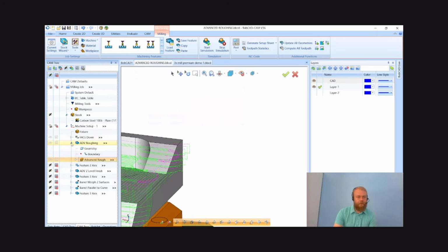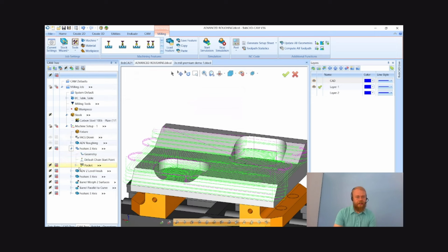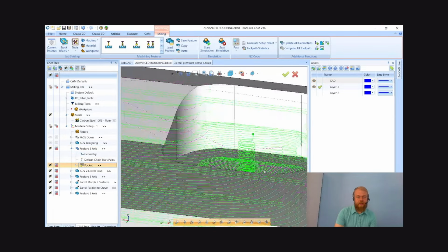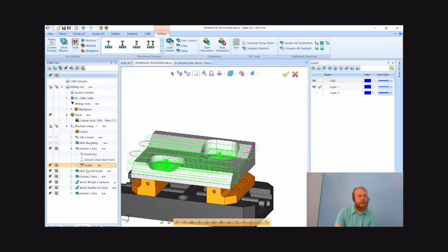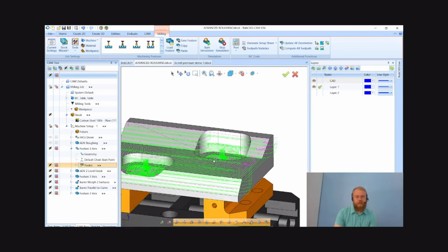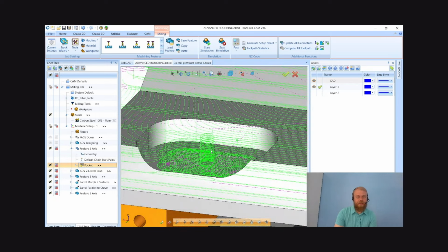And we'll go to the next feature here. I can highlight the operation to show it there at any time, even though it's blanked out. I can show the toolpath just temporarily there and see that it's the pocket operation. I might want to change this up a little bit because I'm spiraling into this one, but I'm also spiraling in this. I could start from the outside.